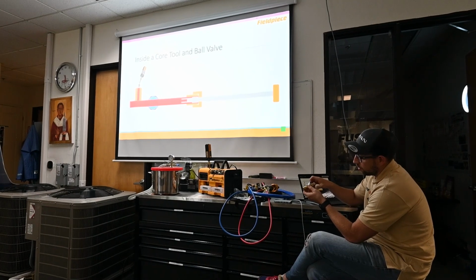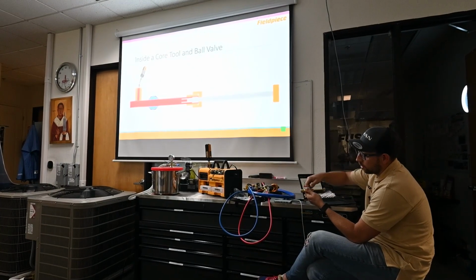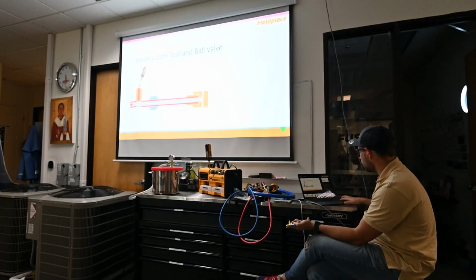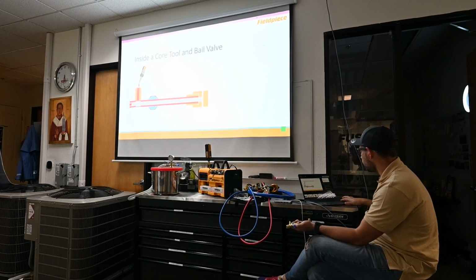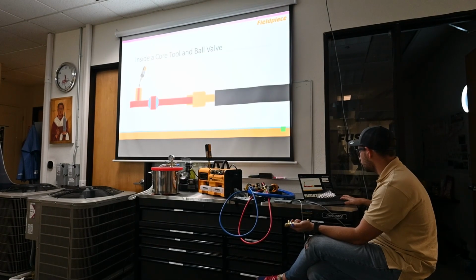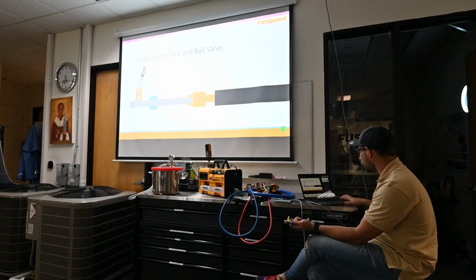Just open and remove the small piece which is installed inside the valve. Open it and close this valve. After that, you connect your hoses and do the vacuum. Pull the stem back with the core. Ball valve closed. Stem and core leave. The hose is connected to the end of the ball valve. The ball valve is open. Pressure is removed by the vacuum pump.